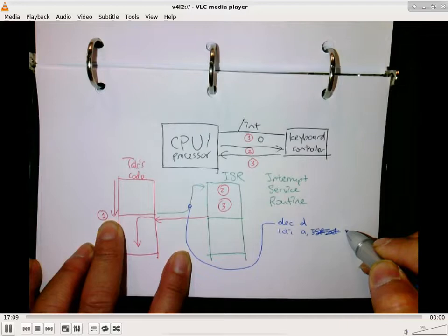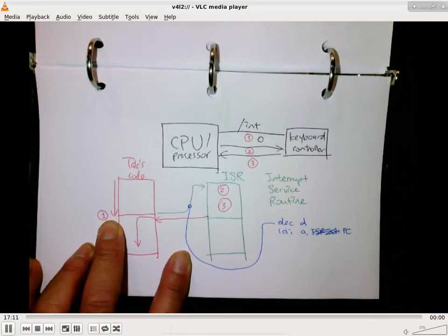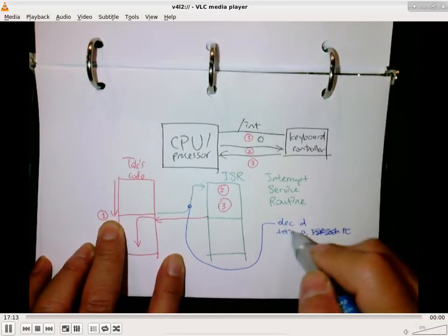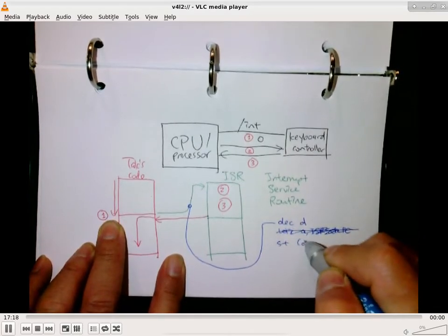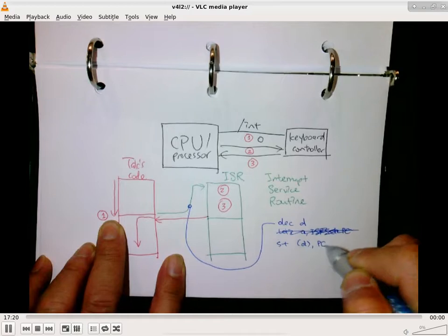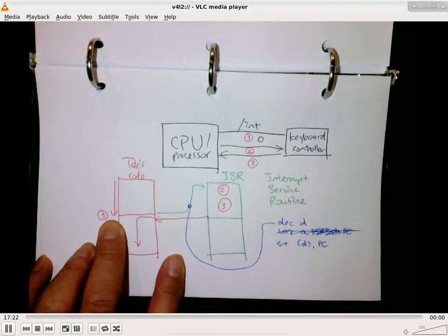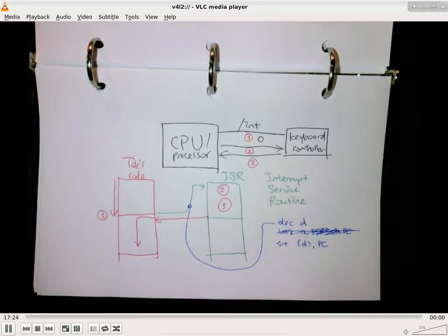So it's basically the program counter. It's just copying the program counter to, okay, take this back. It's STD with whatever the program counter has. Now, we cannot write that code. That opcode does not exist, but what the blue stuff is saying is it is equivalent to doing that, but in the processor itself.